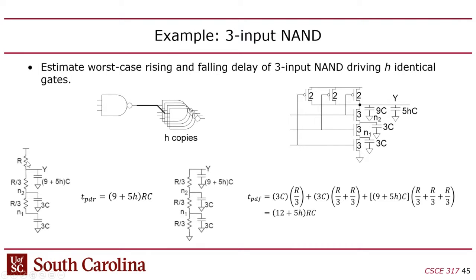Except the only problem with that is I don't remember why they're going through from VDD. Oh, I see. Right, actually, no, sorry, I scratched that. You're only going through 1, actually. You see the Y? I just looked at that wrong. The Y is the output. Notice you're only going through 1 transistor, right? That's because the pull-ups are in parallel. So these guys are disregarded.